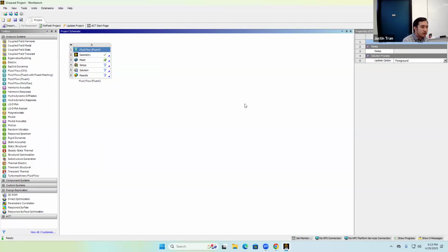Design Modeler wasn't really made for CFD. It was kind of the first CAD software within ANSYS. I think ANSYS made Design Modeler before they bought Fluent. So if you're importing a CAD model and you need to invert it, I would try SpaceClaim or Discovery. All right, any other questions on this step here?